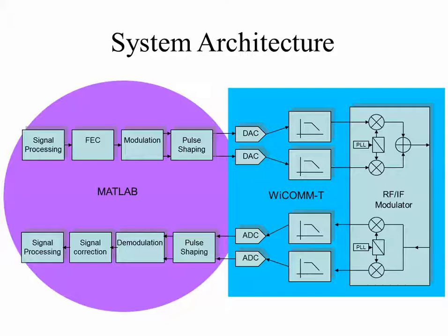After applying the pulse shaping technique, this digital I and Q data is pushed to the hardware through the USB cable. The pair of DAC available at the base unit of the product convert the digital I and Q data into analog I and Q signal. This analog I and Q signal is then passed on to the filter and given to the frequency upconversion section, basically a modulator.